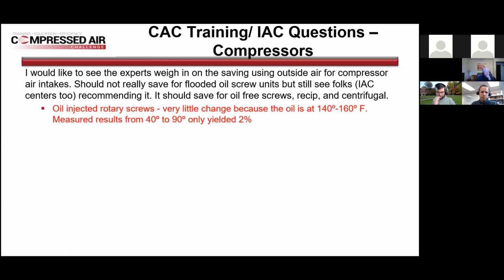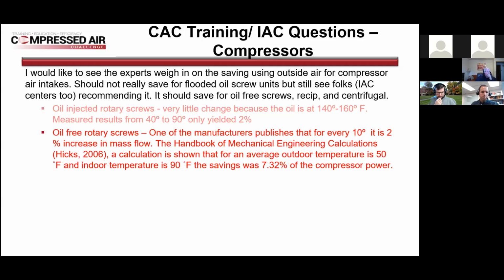I was talking with Frank, and he actually measured this, and on this particular one he found that a change from 40 to 90 degrees only yielded a 2% change. Oil-free rotary screws, on the other hand, one of the manufacturers publishes that for every 10 degrees, it's a 2% increase in mass flow.